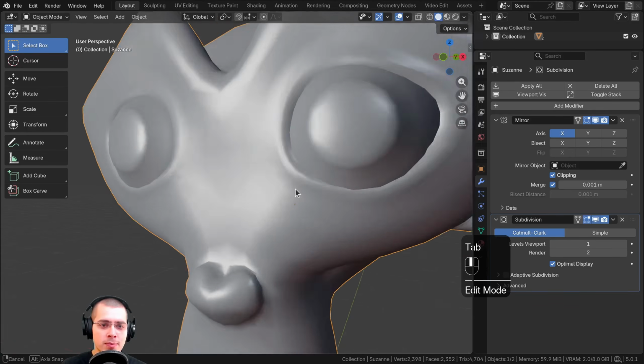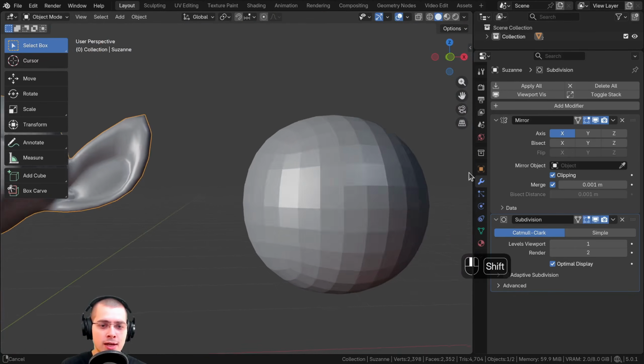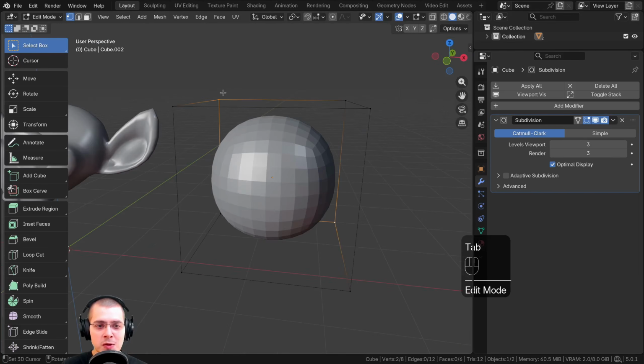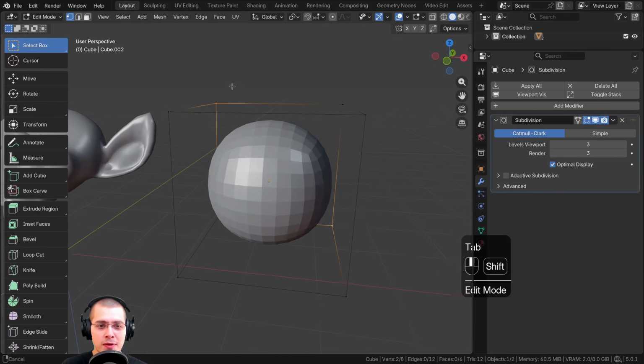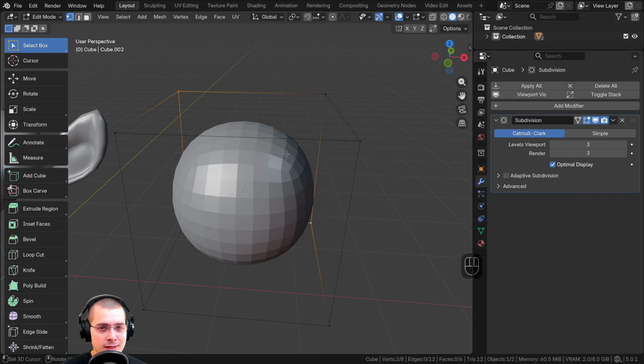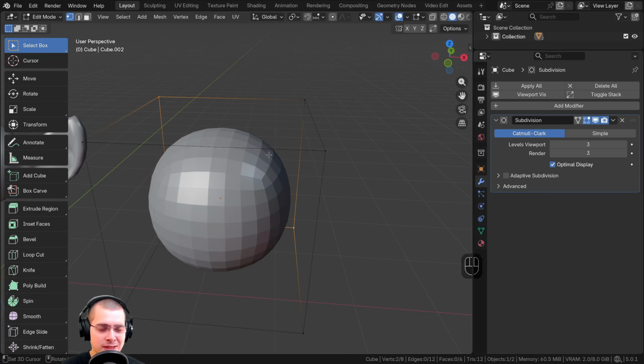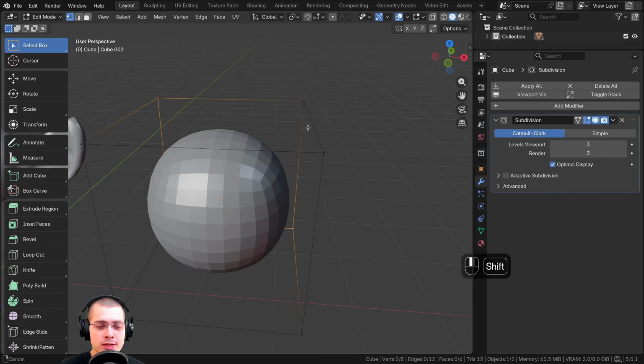So that's why on some spots it looks nice and smooth and flat, but over here on a cube, it's really sharp because it's trying to smooth out this angle. So let's say you wanted to add a subdivision surface modifier to a cube, but you don't want it to actually look like a sphere, you still want it to look like a cube. Well, you could add more geometry and then the smoothing area will be smaller. So what I can do is add loop cuts.